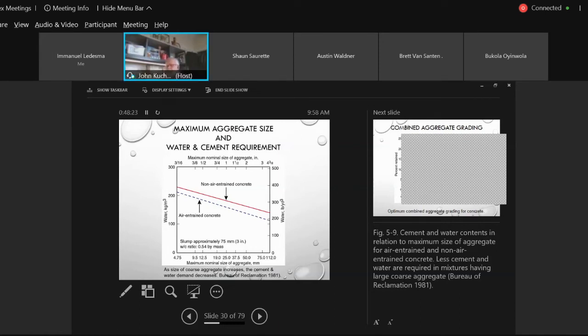And we have that in winter. You know, when your curb or your pavement in the sun right now, it's cold. But it's sunny. You may get some heat buildup. And at night, it freezes. Thaws during the day, it freezes. So you've got various freeze-thaw cycles. So concrete in our climate that's exposed to the elements outside has to be air entrained. Non-air entrained concrete, an interior floor slab, your basement floor slab in your house, you don't need air entrained concrete.